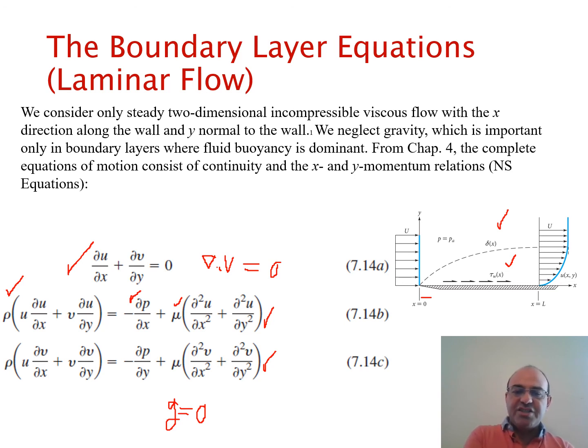So these are the general equations that we have in this boundary layer where viscosity is important. Outside the boundary layer, the velocities really do not change. So the terms that you see in these parentheses will be 0. Outside, the pressure also, for instance for uniform flow, doesn't change. So outside of the boundary layer, we just have a very simple flow, like the velocity is a constant. That's why we are not really concerned about outside of the boundary layer. Inside of the boundary layer is problematic because there is a complex relationship between velocity and pressure.